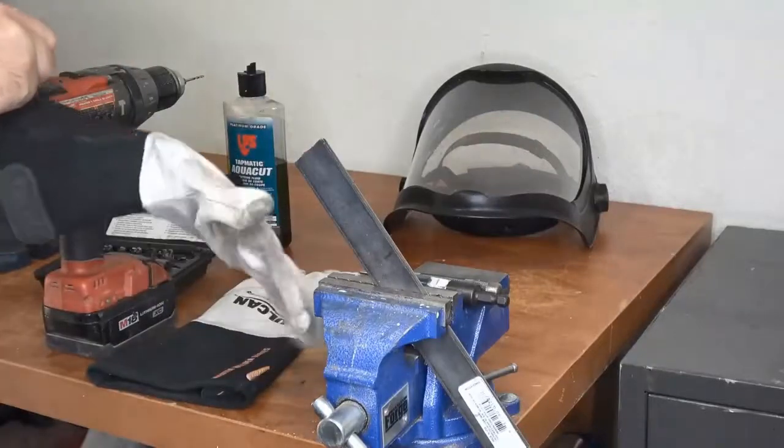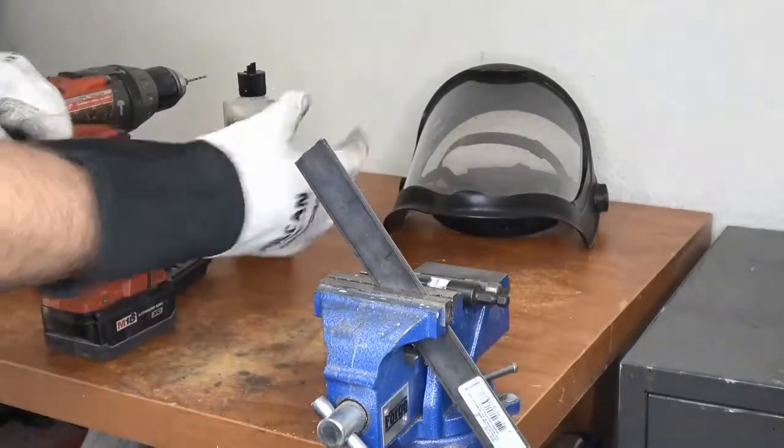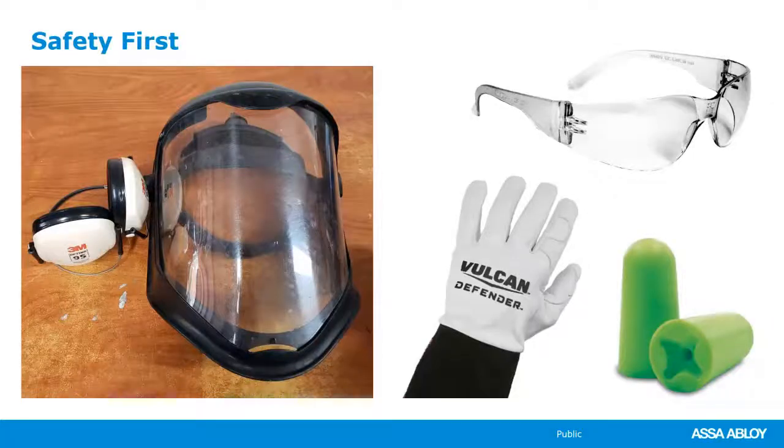So just as proof, putting on my gloves, I will be putting on my face shield. Talking about PPE equipment, these are just a few of my favorites. There are many different kinds out there, and I'm not saying that any are better than others, but if I'm using a drill, a grinder, a rotary Dremel tool or something like that, I prefer a full face shield.